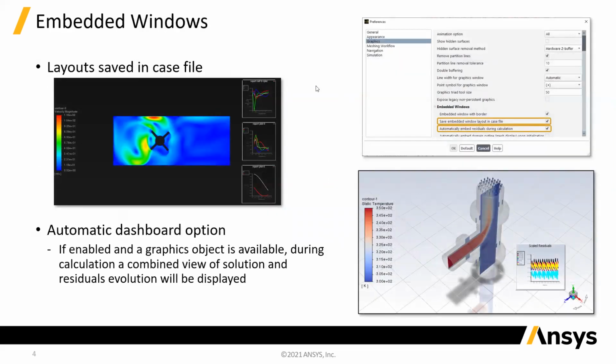Work has continued on the embedding of windows. So recall that we can have monitor windows in the same frame here as we've got a solution variable that's updating. So the key difference here now is that once you've set something up, this layout can be stored to the case file. You can also control exactly what's recorded to the case file in that by changing your preferences.